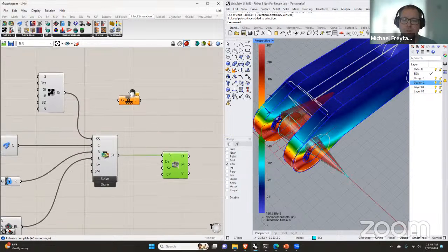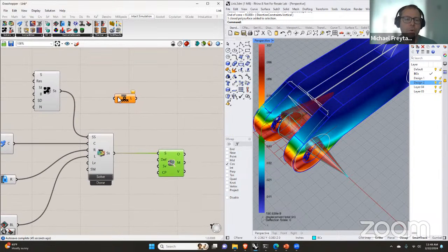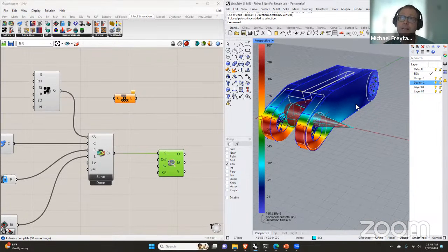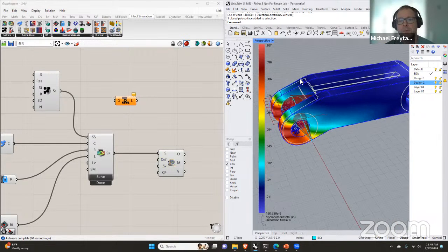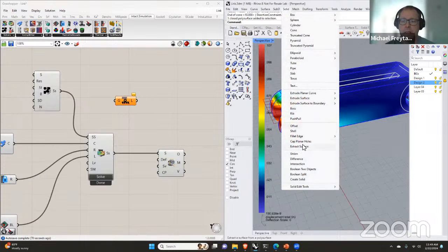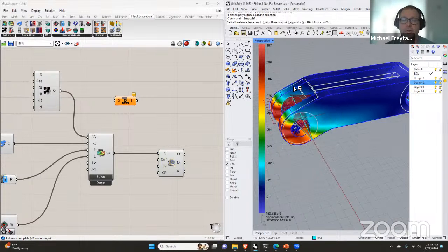So we've got tangent boundary conditions, where you can specify that a particular face is allowed to slide along its tangent, along its plane. If I were to insert one of those, I can specify, say, that I want this surface to only slide along its plane. What I can do is set a boundary condition on that face, and choose this surface.